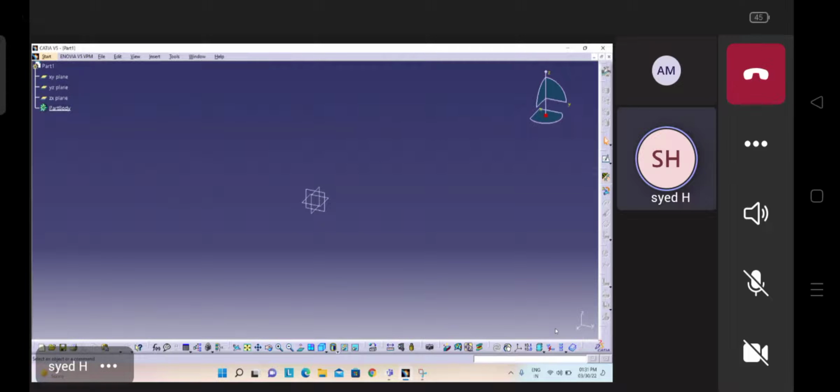What material cost is required? If you go for casting, so much cost will come to you. Why? Because you have to melt the material, the time cost, so many things. So if it is a simple channel with a uniform thickness, which we can easily make with sheet metal parameters, then why should we go with casting?